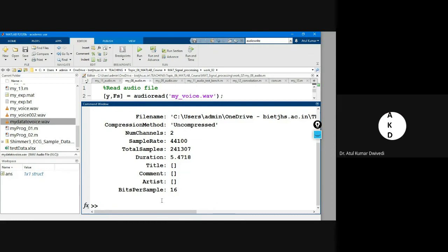We can use the spectrum analyzer also. Yes, very nice. By transforming, like the Fourier transform, FFT or DFT, we can know the frequency of the signal, and then we can decide the frequency of sampling. Because FFT will give the frequency of the signal, and for the sampling frequency we have to decide it ourselves.